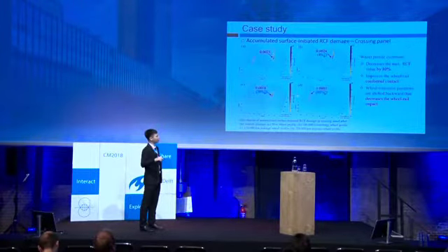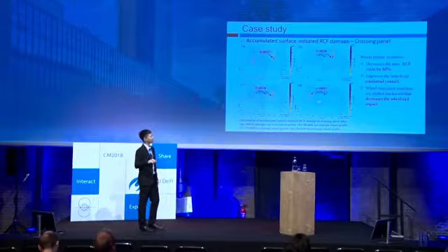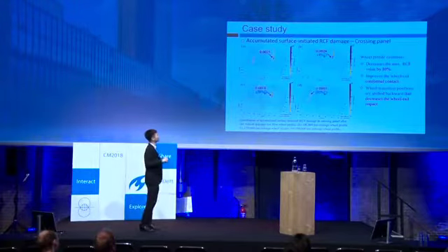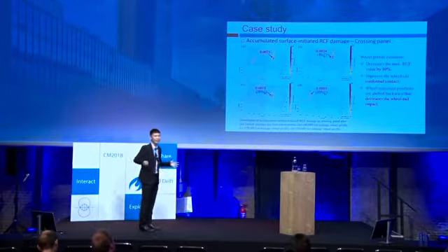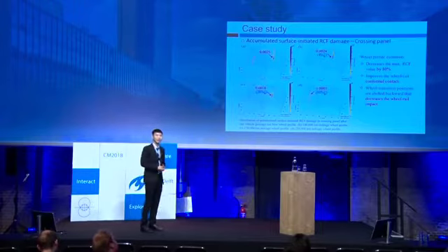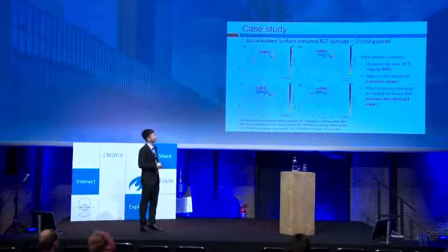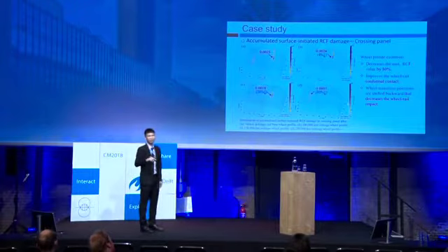It is speculated that there are two reasons. The first is that the wheel profile evolution may improve the wheel-rail conformal contact, which enlarges the contact patch and decreases the contact stress. And another one is that the wheel transition positions are shifted backward with wheel profile evolution, and that decreases the wheel-rail impact in the turnout area.